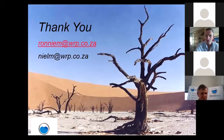So there's a guideline on that, and then you add those two together, and that gives you your expected minimum night flow. You then compare it to your measured minimum night flow, and if the two numbers are reasonably close together, then you know that you don't have a major burst problem. If the two numbers are quite far apart, that gives you an indication that you do have a burst problem in that zone. And the minimum night flow is, in my view, one of the most important factors that you can look at when managing leakage in a zone. It is by far the best indicator of leakage in a zone. And it's good to be able to get an estimate of what you would expect so that you can determine whether or not you have a problem and how big that problem is. So it's a very good indicator, and it deserves a lecture on its own.